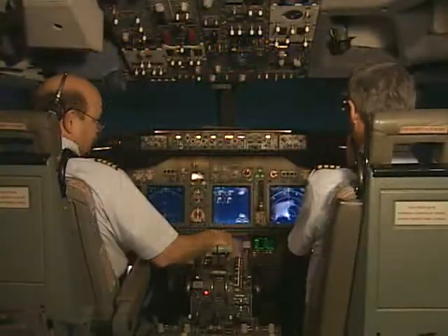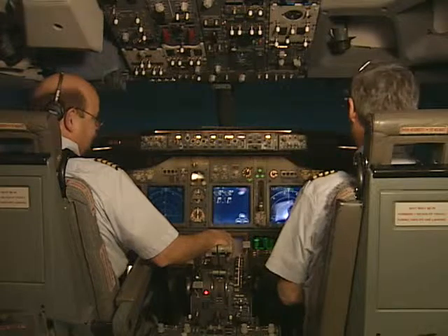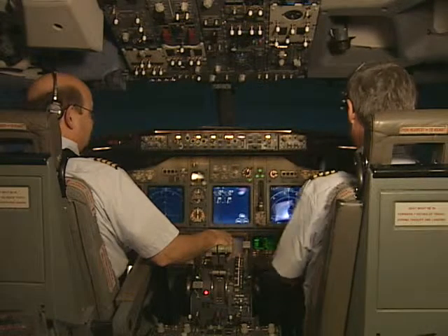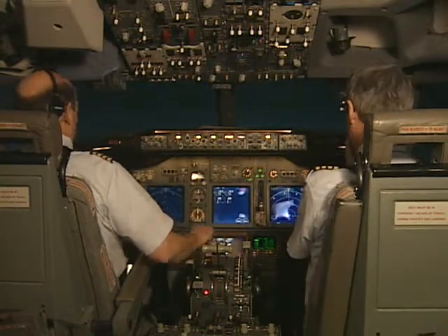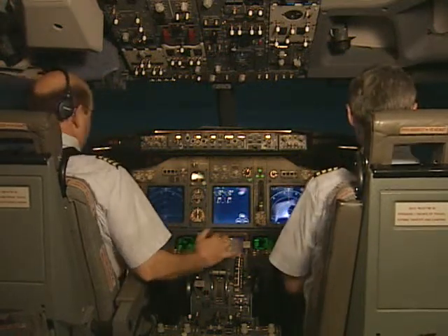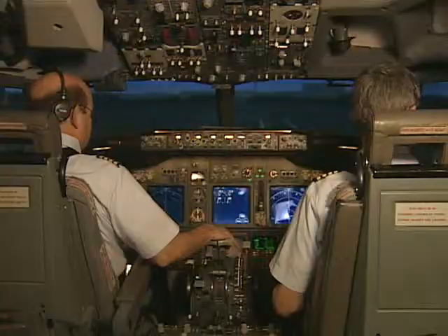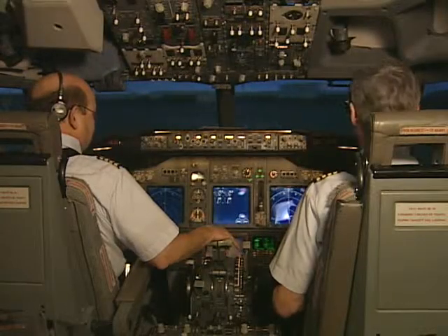Actual airplane weight during operations is the weight of items such as fuel, crew, catering, passengers, baggage, and cargo added to the basic empty weight. And airplane CG during operations is the result of the distribution of that additional weight on the basic empty weight CG.